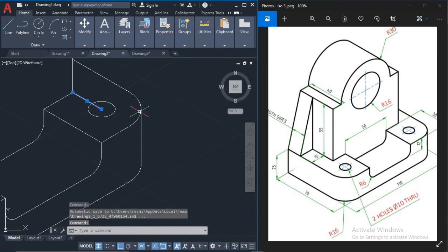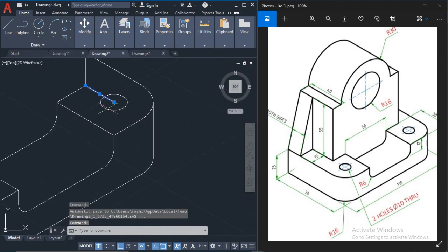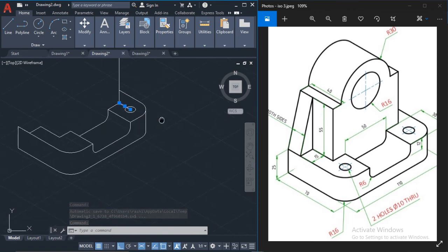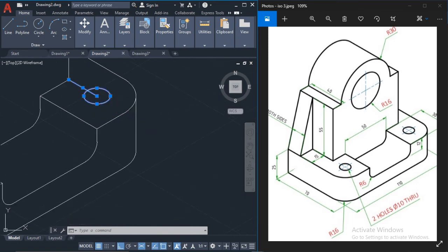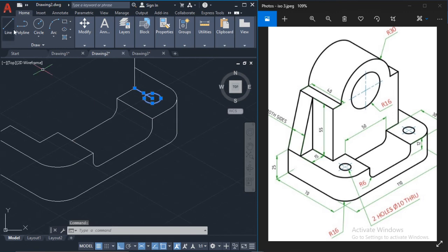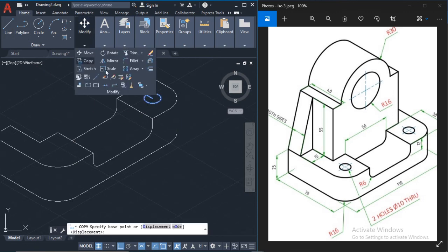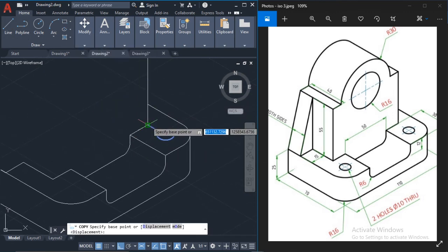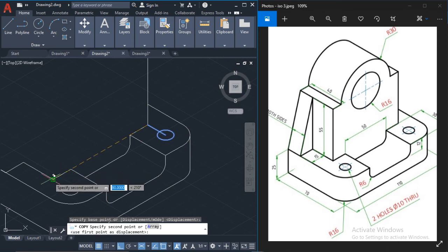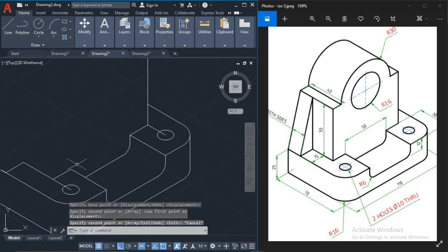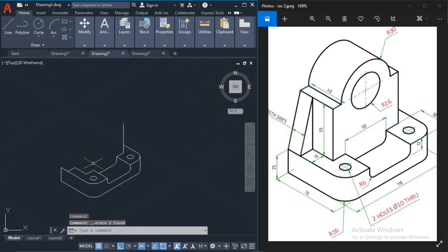Yeah, so there. I'm not going to delete that line. I can do this. I can simply just copy from here instead of draw the next isocircle and bring that to the right there. Alright, so it lines up with this edge and that edge, okay, and then I can delete these two lines, and there I have my two isocircles.